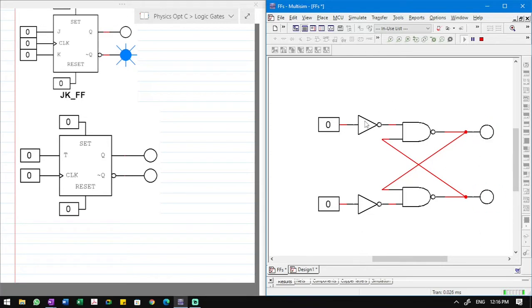Now these race conditions have been set up here, so I could eliminate that race condition by doing that, right? So this is S, this is the output Q that I'm focusing on. Let me remove that one there, right? So right now it is in a set state, so nothing I do to S is going to affect that output Q, the one on the top, on the output side, right? Because it is already in the set state, nothing I do to S will affect it. Whether I change S from low to high or high to low, it doesn't matter.